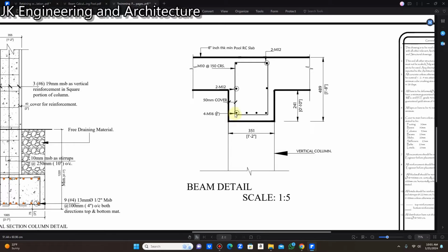If you notice, in the tension zone of the concrete, I have 4 number 5, or 5/8 inch bars. I'm going to show you how I get that to be 4 5/8 bars in the tensile zone to carry the load. And here we have this bar, this bar, this bar, and this bar, and that is for temperature and shrinkage. So it's temperature and shrinkage and flexural bar.